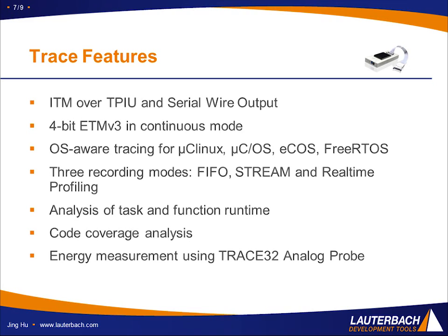As to trace features, ITM generates information about the performed read and write accesses assisted by the data watchpoint and trace unit. The ITM trace information can be read out over TPIU and serial wire output. 4-bit ETM tracing in continuous mode is supported. Operating system-aware tracing is supported again for operating systems such as uClinux, uC/OS, embOS, FreeRTOS, and so on. Three recording modes are available to record the trace information.